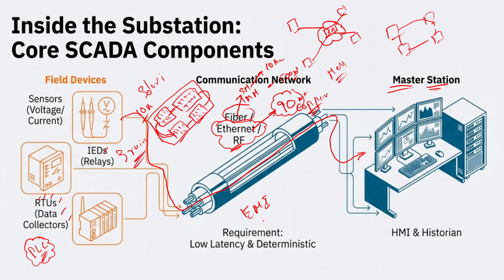This is a very important concept, called electromagnetic induction, right? For example, if we have multiple cables running from multiple RTUs, say you have 10 RTUs within the same facility, you cannot run the same cable in the same path, because when you do that, there will be electromagnetic induction. And also you cannot club the data cable with the power cable.